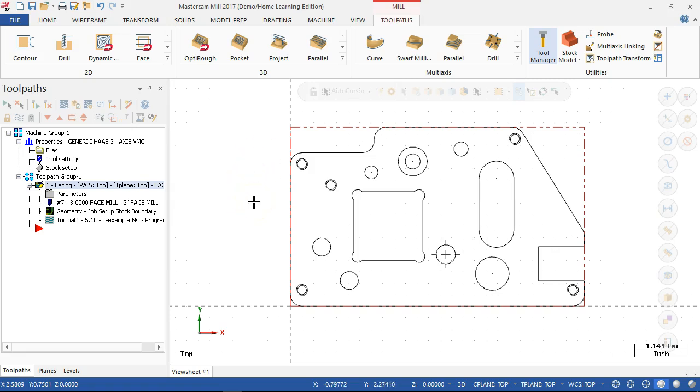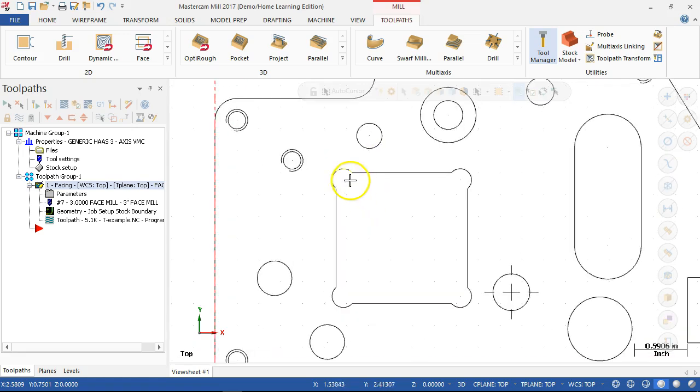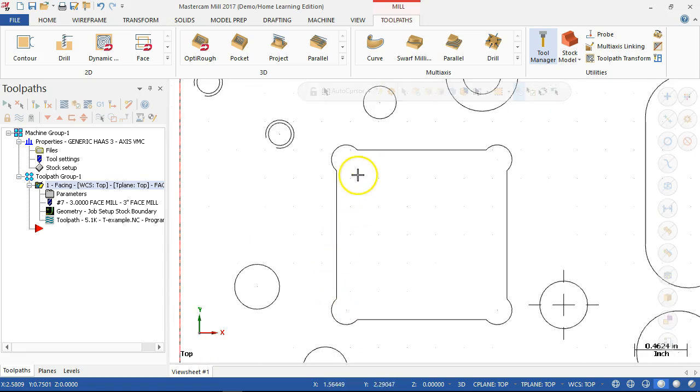All right, so in that case, then we're going to go to the pockets. The pockets on the interior. In this case, when I did this video, I said I wanted my truncated Mickey Mouse ears, my overruns. A lot of times designers will just put a drill point into that corner, you feed up to it, you run into it, and you come out. The issue there is that sometimes the tool still tries to get into it, and we've still removed a lot of material.